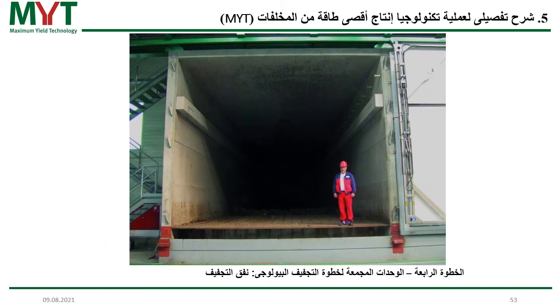Just for showing you the size of one tunnel, it's quite big. The waste is put in, as I told you, from the ceiling. And then it stays in one tunnel for only 4 days. Air is blown from the bottom to the top through the waste material so that the microorganisms are supplied with sufficient oxygen.